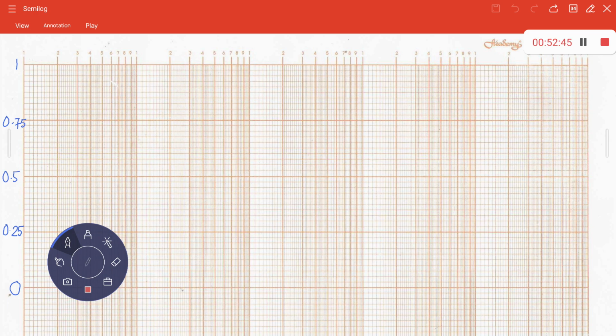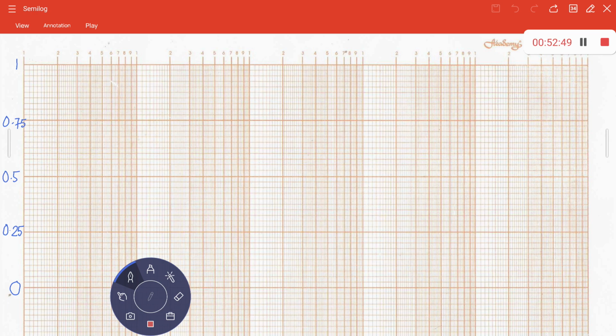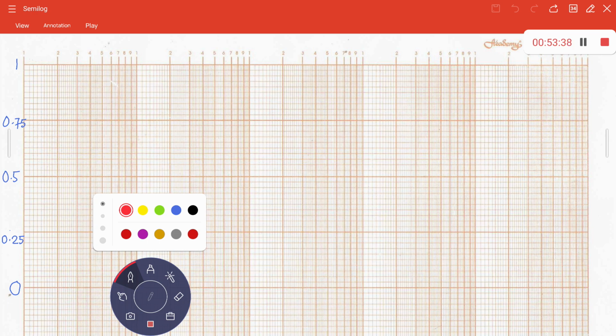So first one is 10 hertz. At 10 hertz, the value is 0.278. So this is 0.25, and 0.5 is here. What is the difference if you consider small steps? 0.25 by 10, that is 0.025. Right. So where to place this 0.278? Only one small division above. This is 0.2, this is 0.25, and at 10 hertz, let's take a different color. At 10 hertz, what is the gain? 0.278. So this is this point. This is 1 point, right?